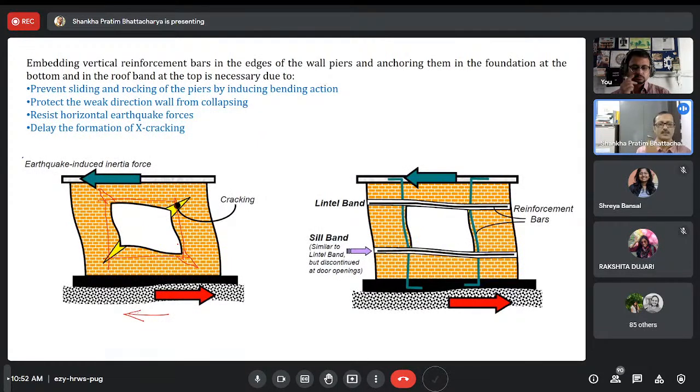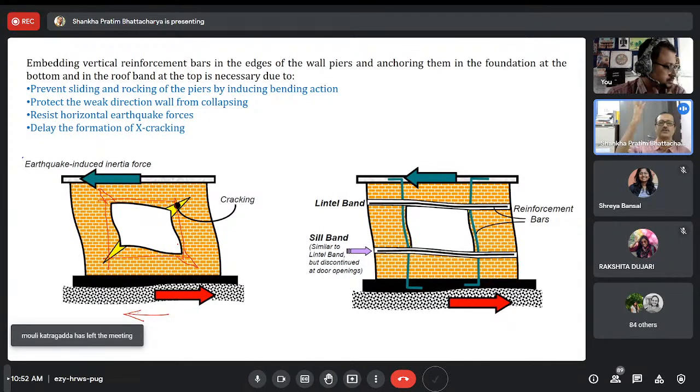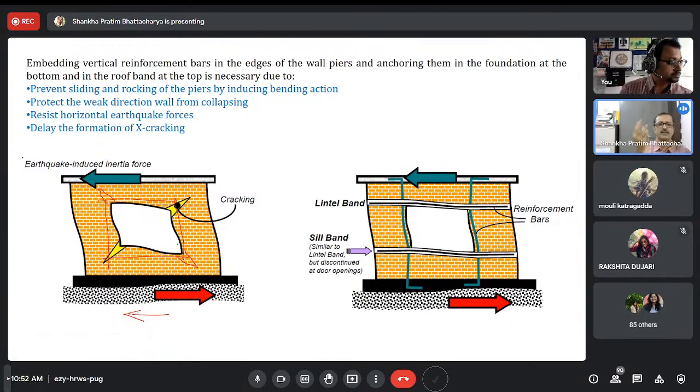Actually, because of the development of tensile stress or tensile strain, the crack is going to generate. So give some steel. Whatever tensile strain occurs initially will not directly jump to 100. It will start from 1 to 5, 7, like that, and increase. Initially the strain is developing, and the steel is arresting and absorbing it as a ductile material property. The propagation of the crack will be slowed down. So I told you that 30 seconds will be elongated to 45 seconds or so. The steel is going to help you, so you have to give some kind of steel reinforcement.